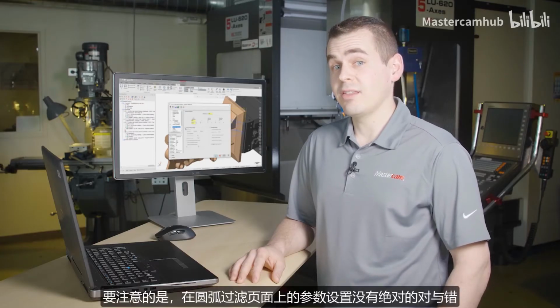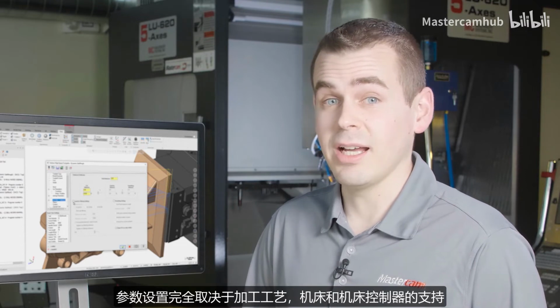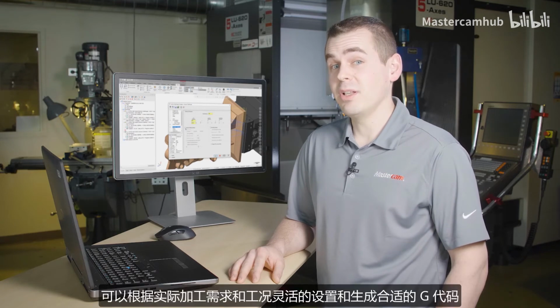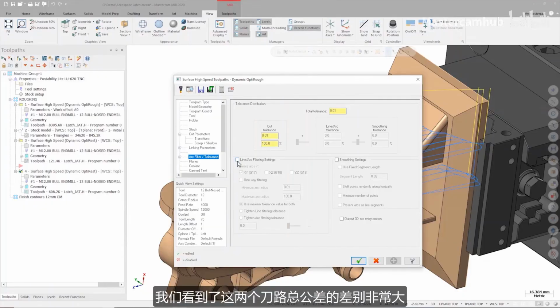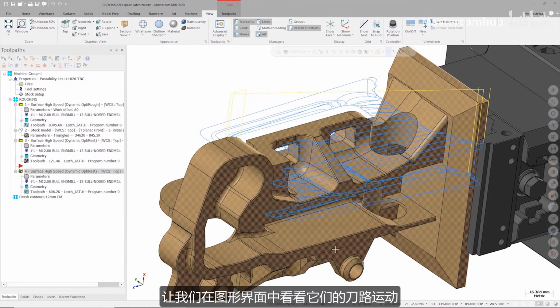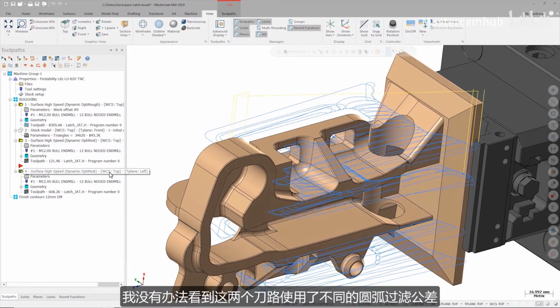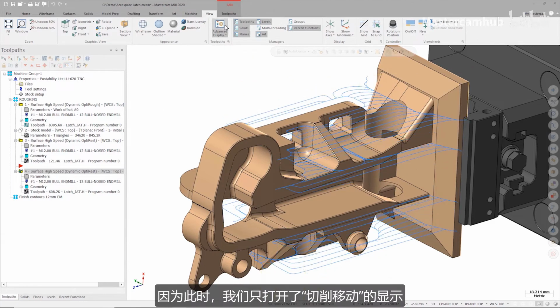It's important to understand that there's no right or wrong when it comes to the settings on the arc filter page. These settings depend completely on your process, the machine you're cutting on, and what your machine's controller wants to see. Mastercam gives you the flexibility to tailor the code to your specific needs. Since we know that the tolerance settings for these two toolpaths are very different, let's look at the toolpath motion in the graphics window. You'll notice that if I turn on both toolpaths, I have no way of knowing that they are using different arc filter settings, since they look identical. That's because we're still looking at only the feed motion.